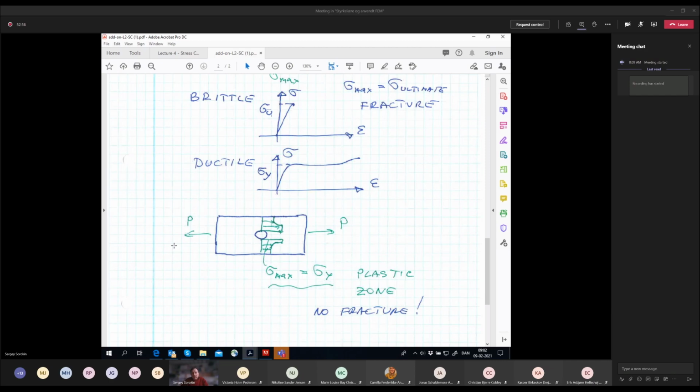So first of all, in the design of any structures, we avoid using brittle materials if we are dealing with stress concentration factors. For example, of course, we can use cast iron in some situations, but it's not a very good idea to drill holes. And we definitely don't use glass for structures exposed to loading.